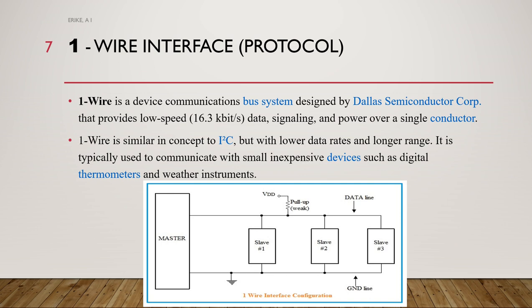Now, one distinctive feature of the bus is the possibility of using only two wires, which you can see in this particular diagram. So you have this, I'll call it positive line, and then we'll have this one. So the data line is actually connected to the VCC through a pull-up resistor, and then you will have the ground.